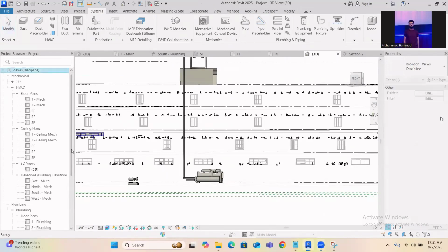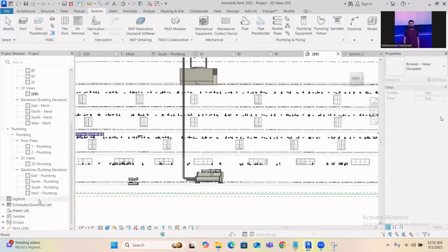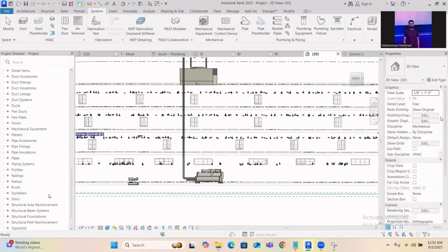And one more important thing is when you are doing pipe working or duct working, here you have these families, okay? And if you have to define the supply duct and return duct, you should give them proper color code so that if you are doing any calculations, it might help you. Let me show you for that.